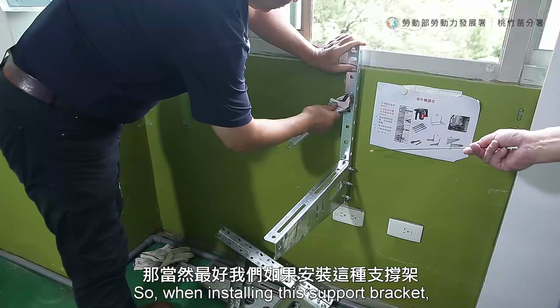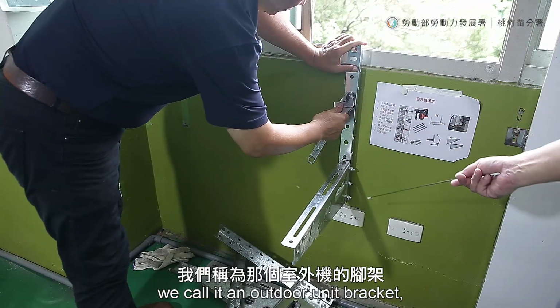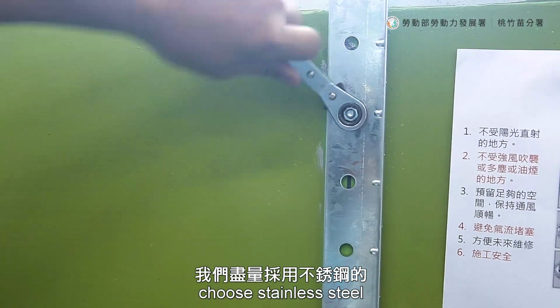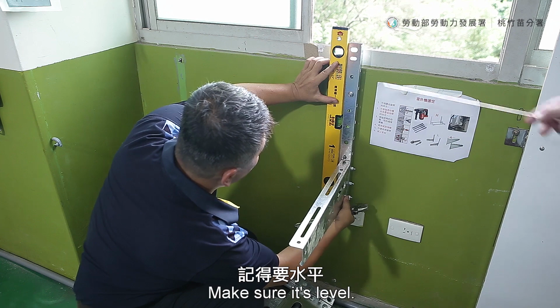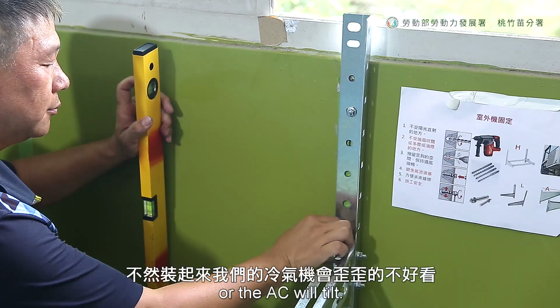So when installing the support bracket, we call it an outdoor unit bracket. Or when installing the screws or the expansion bolts we just mentioned, choose stainless steel, because rust can make it hard to remove the AC in the future. Make sure it's level. This should be level, or the AC will tilt.